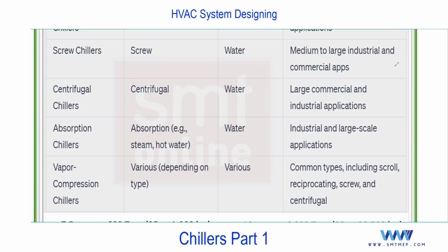If you talk about the classification according to the condenser, according to the type of cycle, or according to the compressor. So if you talk about compressor, again, that depends on the capacity also. We'll discuss next only the type of compressor and the range for the compressor as per the type. And next, if you talk about the application point of view, mostly for residential, commercial, or even for industrial, you'll find vapor compression cycle. But vapor absorption, mostly you'll find for industrial application, not for the residential or commercial projects in actual practice.